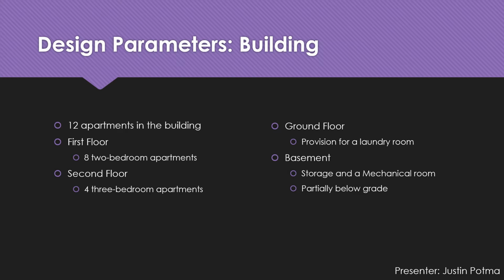The proposed construction site is a rectangular plot of land with an area of half an acre that has road access on one side and land on the other 3 sides. The footprint of the 12 apartment complex is planned to be 60 feet by 120 feet. Any existing building structures on the plot have been slated for demolition, and the bore well used to supply the building is to be located close to the proposed site, somewhere within 40 to 300 feet.